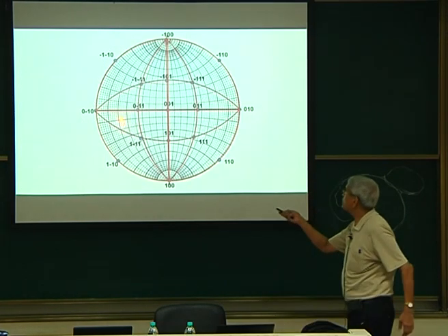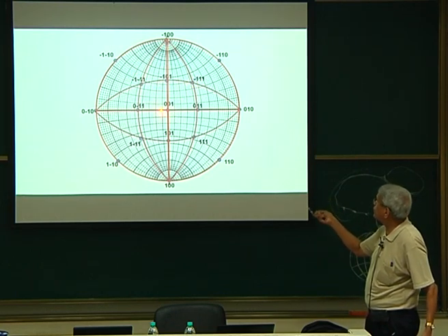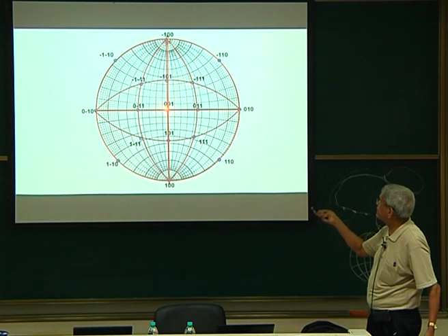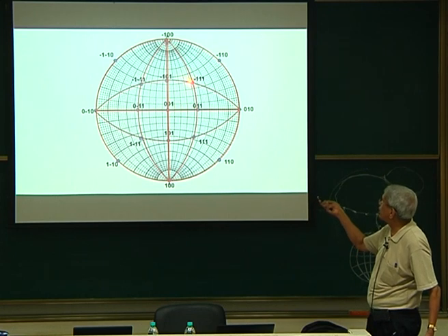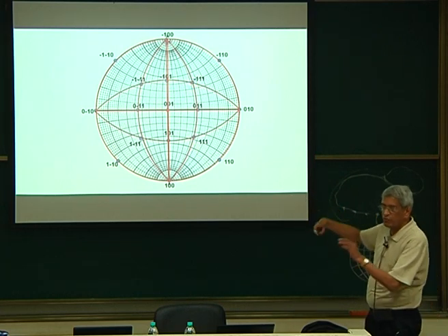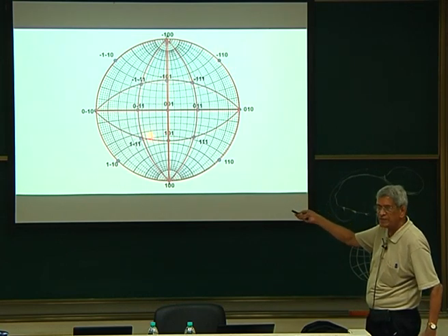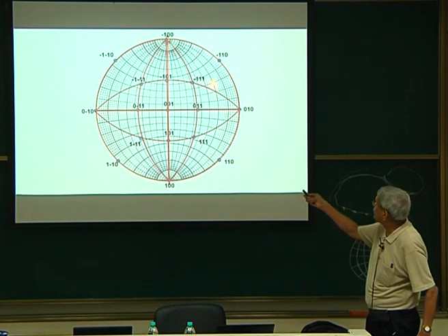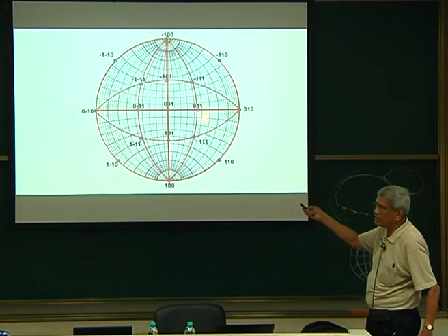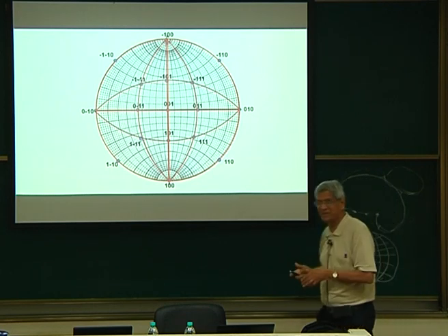This is exactly what is being shown here also, for different angles if I want to measure it. But from here to here, because this is at one particular latitude and longitude, and this is at another one, I have to rotate this and bring it so that this point comes on this one. By putting a pin here, if I rotate it in this direction, then this point will come on that, because this will remain at the center. Or I can rotate it in this way so that this point comes here, that way the angle could be measured. That's what I said, to measure angle we have to do that.